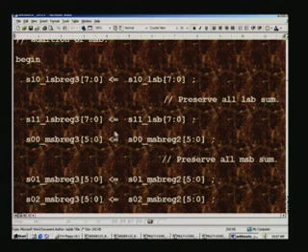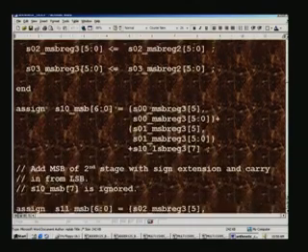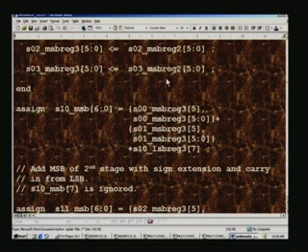In this case, this is the second stage, so there will be only two outputs here, and this is the MSB. So we need to preserve the MSB here, that is LSB and this is MSB, and continue the addition. As far as the MSB is concerned, we are going to add in this fashion. For example, this is the second stage, so we have added only the LSB earlier, and we have to continue adding the MSB along with the carry that was generated in the LSB addition of the first stage output, and that is this one here.